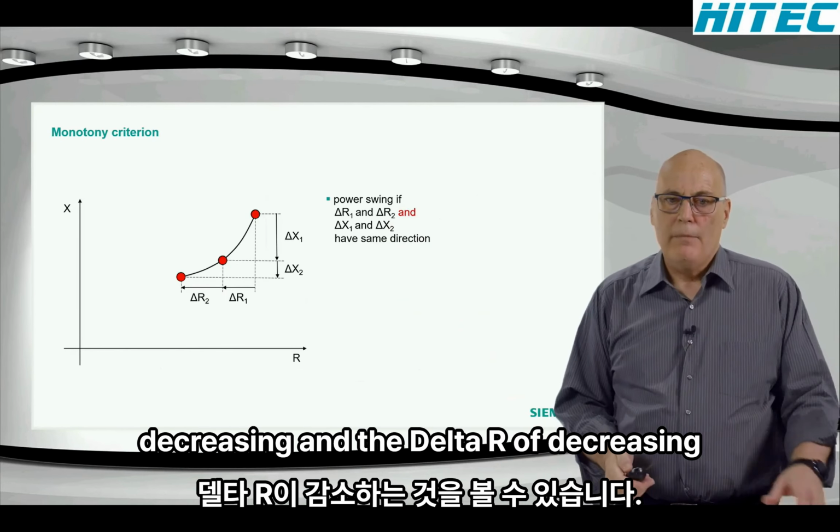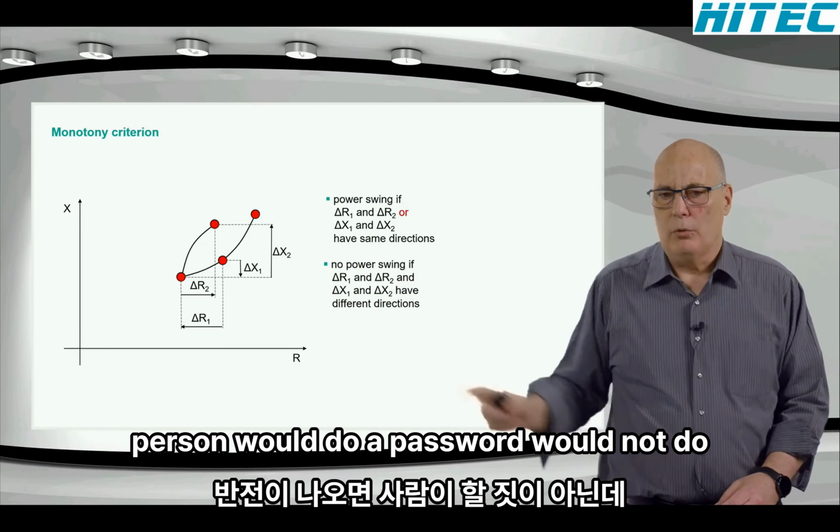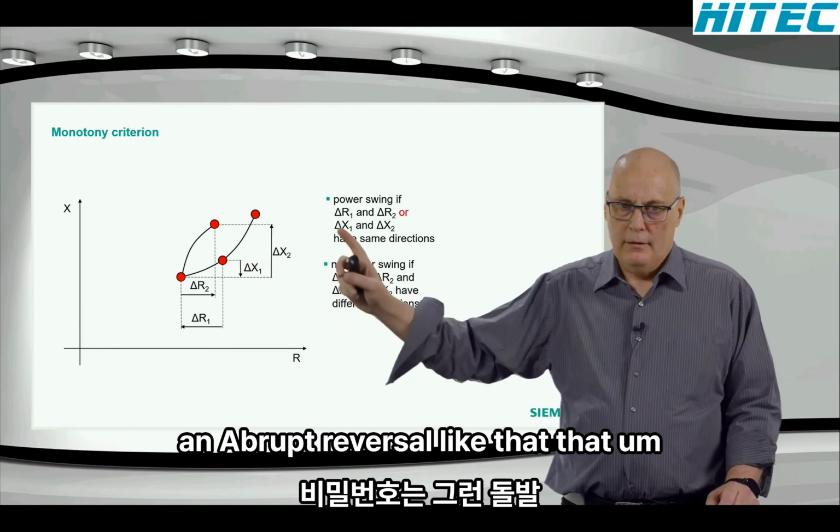This would still be a power swing. This is a fairly monotonous movement because only the x changed direction, not x and r. That would be a normal smooth trajectory, as one would refer to that. On the other hand, if you get an abrupt reversal like that, that is not what a power swing would do. A power swing would not do an abrupt reversal like that. That would be a criteria to reset the power swing blocking, as one of the criteria, not the criteria. It's a number of criteria working in parallel.